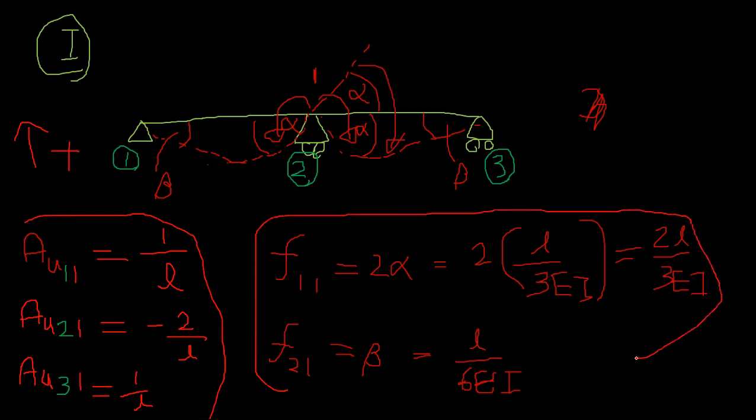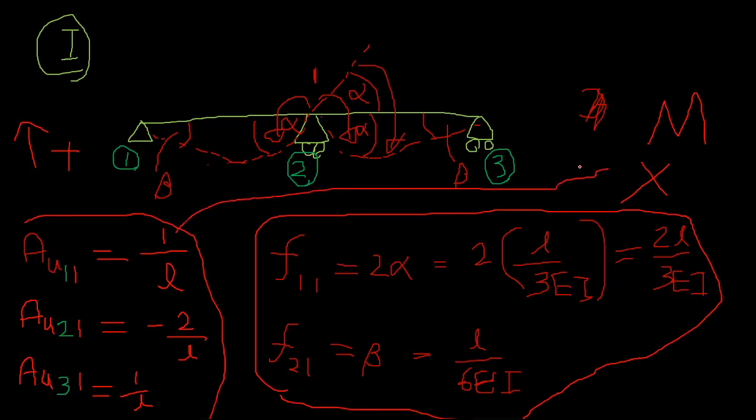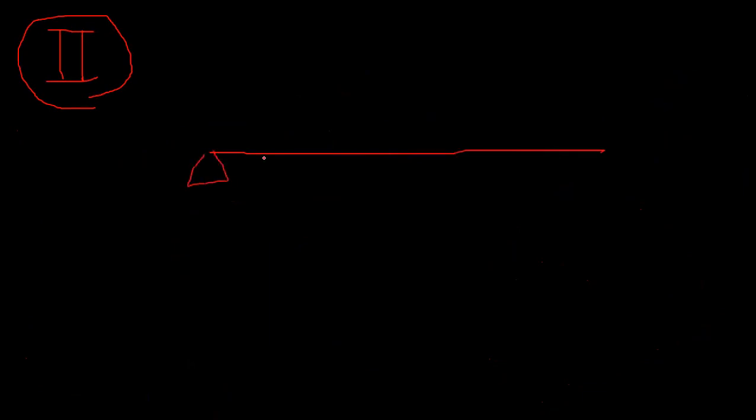Displacement, so actually the flexibility, why? These are the displacements per unit force. So this is going to be finally multiplied by MB, right? So then we are getting the corresponding deflection. If this is for a unit force, what it will be for MB force, right? Very simple. So we are applying the second redundant now. It's here.